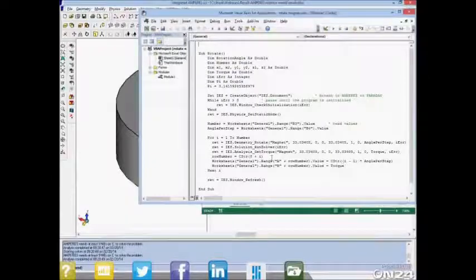But of course we can add lots of details in here to account for things like the nature of the coil, so that we pick up the induced voltage, use that to generate a specified current in the next step, and we can also use mechanical considerations to say, okay, based on this torque, based on friction, based on the moment of inertia, and so on, we'll make mechanical predictions as well.